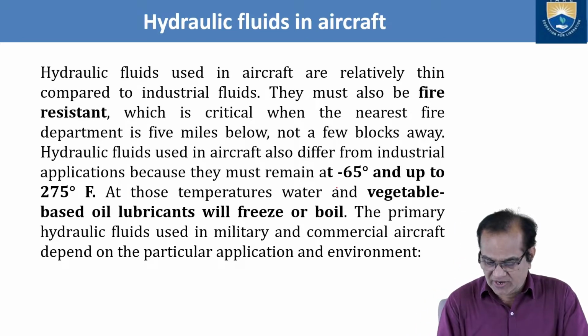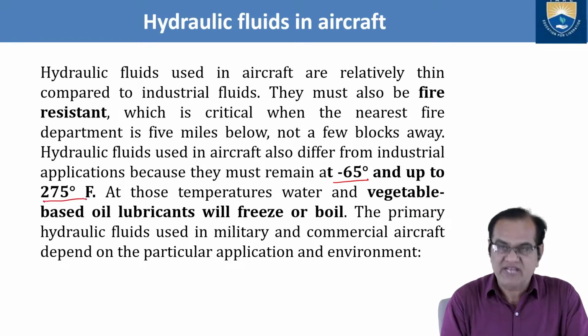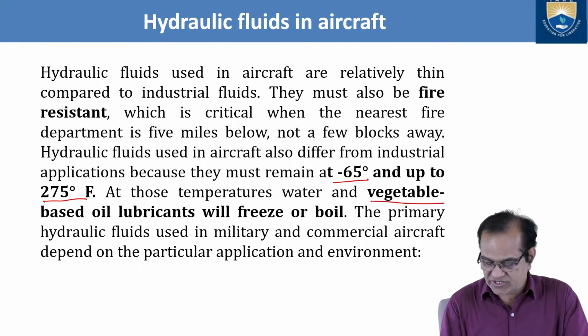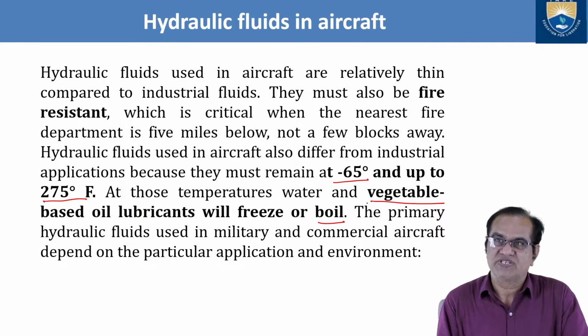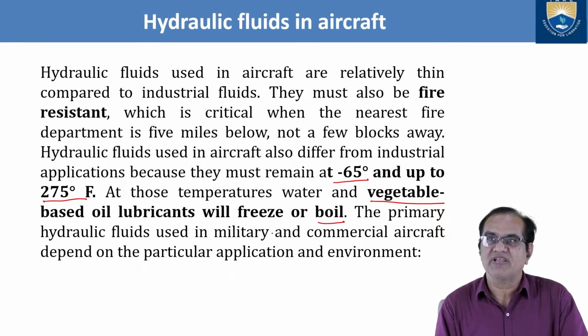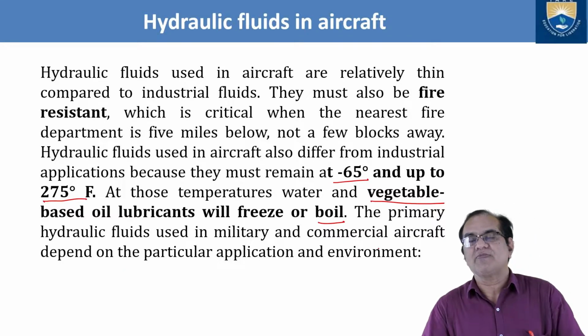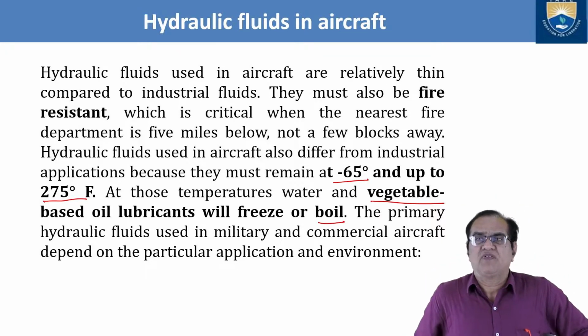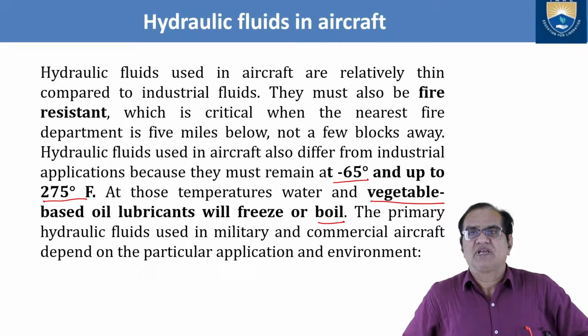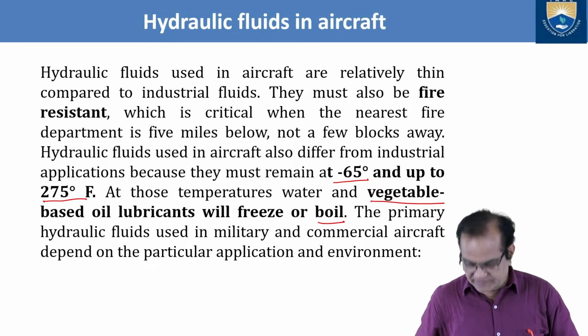So if our aircrafts are used in this range, our vegetable-based lubricants will freeze or boil. If it is high temperature, it will boil, and if it is low temperature, such as minus 65 degree Fahrenheit, it will freeze. The primary hydraulic fluid used in military and commercial aircrafts depends on the particular application and the environment. So what type of system we have to use depends upon in what situation we are going to fly the aircraft.